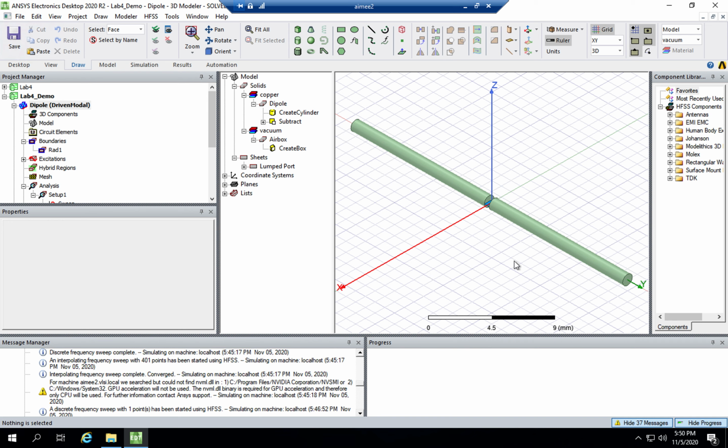So for a dipole antenna, the E field is going to be parallel to the dipole. So in this case, the polarization is in the y direction. Of course, if your dipole is in the x direction, the polarization will be along the x, along the dipole. But in this case, the polarization is along y. The next part is to plot the 3D radiation pattern, which is the total gain, or I'm asking you to plot the total gain at the design frequency, and what type of radiation does the dipole have.